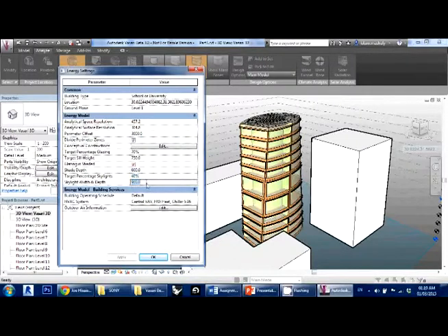And you can change the width and depth of the skylight. So for example, if you want one skylight on the roof, you can start adjusting this number to match the skylight that you have. For example, 4,000. So now that I've increased the number to 4,000, each skylight has 4,000 of width and depth. You can see here that the roof has only 2 skylights.